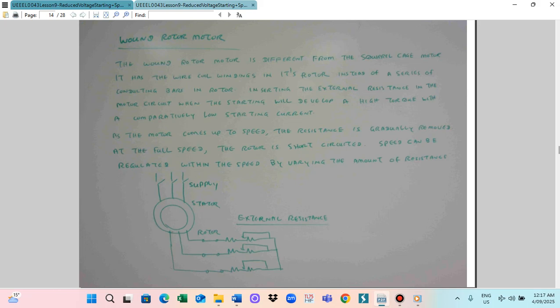Induction motors draw a starting current that is higher, about 2.5 and sometimes up to 5 times the normal full load current. So this starting current needs to be reduced by connecting starting resistance. That is the primary resistance starter, where we connect a series resistor to the stator circuit so that the starting current will be less.